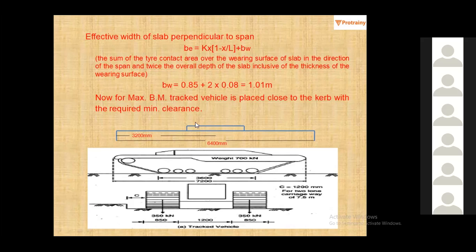So minus, you have to find out this जो इसकी intensity, and you have to multiply this intensity with the remaining half of the distance. So it's like 0.25 into 4.76. Then only you can find the maximum bending moment, which is 113 kilonewton meter. Okay, sir. ठीक है? This is the process. Now you have to put the values and calculate it on your own. So that is going to be 113 kilonewton meter.